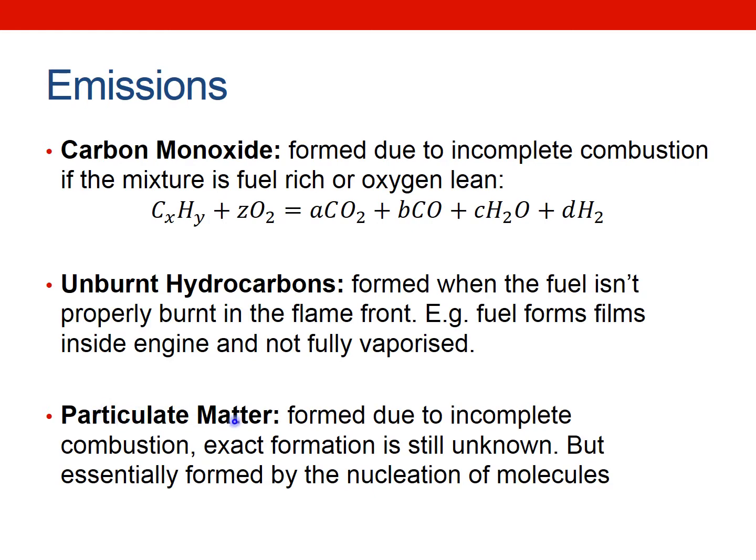Particulate matter. Now, this is formed due to incomplete combustion again, and particulate matter is just carbon, so it's a hydrocarbon where all the hydrogen has been removed. Its exact formation is still unknown and up for debate, but essentially it's formed by the nucleation of carbon molecules. So you have one bit of carbon, and then more carbon sticks to it, till eventually you get particulate matter, which is a whole bunch of carbon, which is then exhausted out.